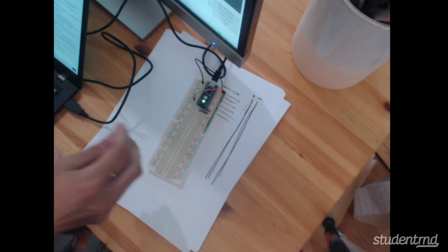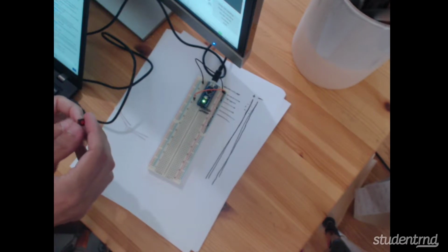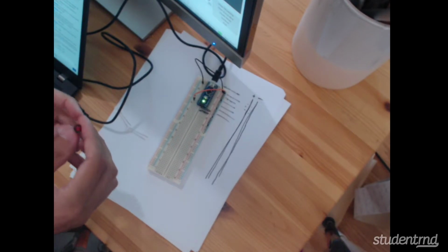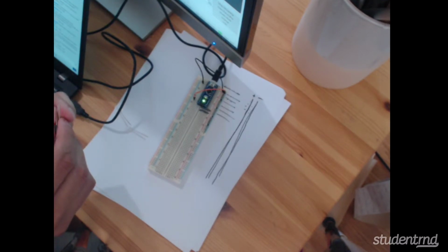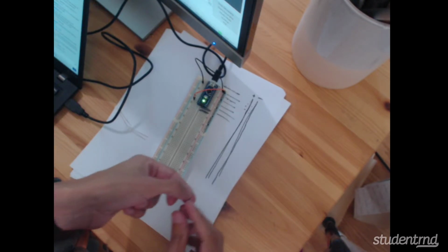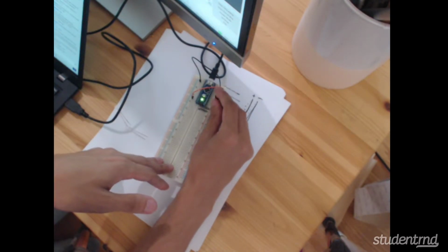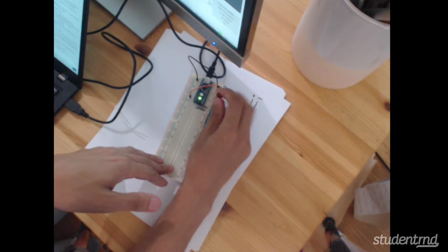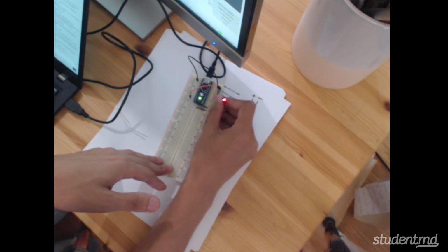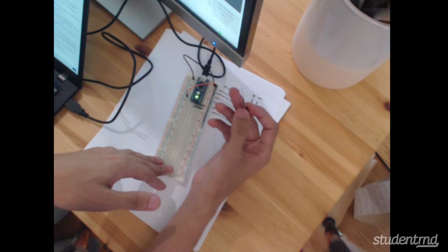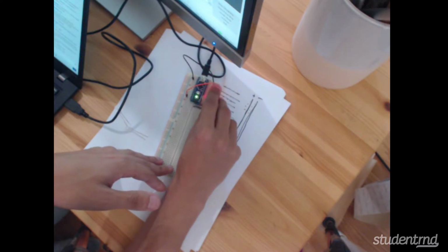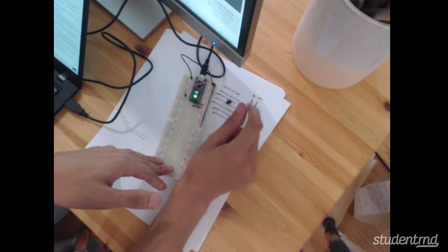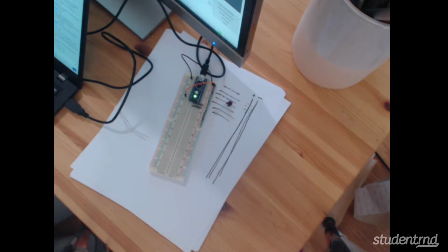So we have some LEDs. You've probably heard of LEDs from the light bulb. Most people have LED light bulbs now, or at least a lot of them. There are two leads. I believe one of them is a little bit longer than the other, and I believe that the longer one goes in the negative or 0 side, and the other one goes in the positive side. And if that's wrong, nothing bad is going to happen. So let's just try it both ways. There we go. Okay, so I was wrong. The longer one goes in the positive side. So we can go ahead and put those in. You can see it lights up. Now the problem is, this actually gets really, really hot really quickly. And this is why I wanted to cover that thing called Ohm's Law.